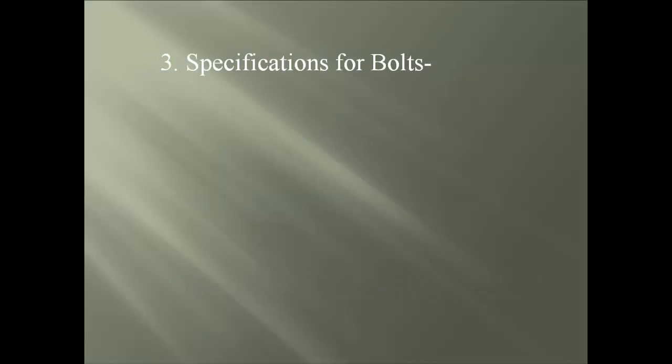The last topic of the segment is the specifications for structural joints using ASTM A325 or A490 bolts, which gives the strength requirements of the slip critical connection, a modification for round-headed A490 bolts, and simplifies the use of plate or hardened washers, to just mention a few items.